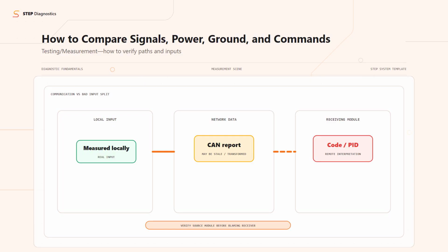To diagnose data disagreement, test all three circuit legs: reference power, ground, and signal. Use a meter or scope to back probe at the sensor, connector, and module. Look for offset, voltage drop, or loss under load. Repeat under the same operating condition that triggers the mismatch.